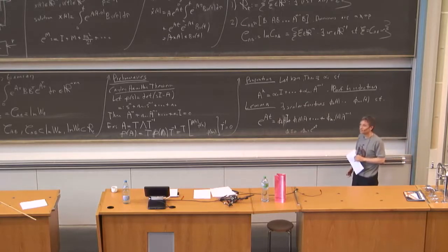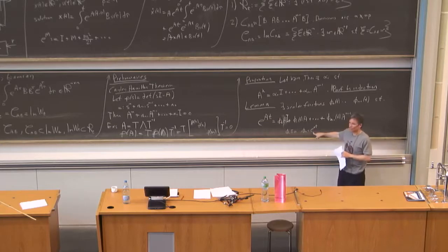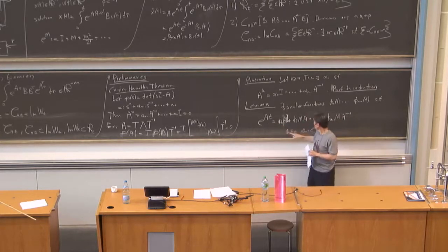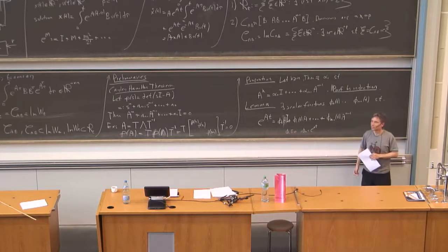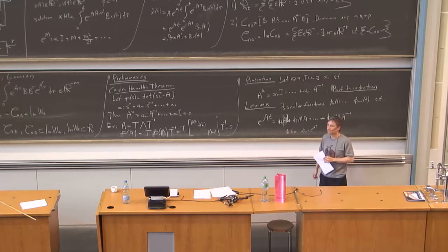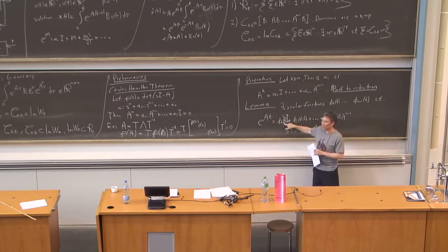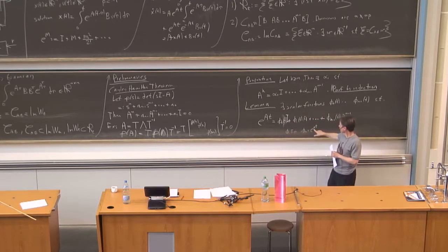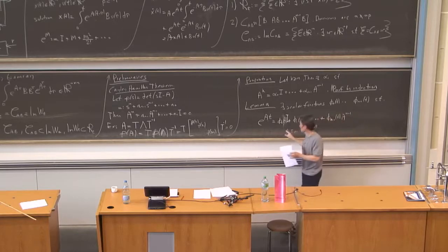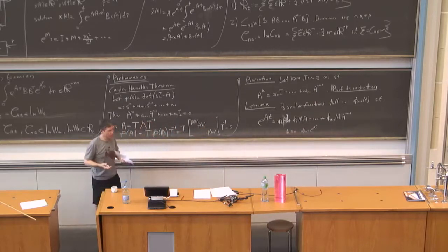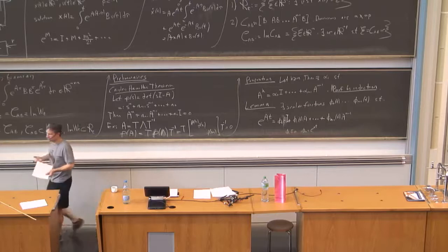I've just given you the answer right here. If A is a scalar, why not just pick all of these equal to 0? E to the at is just equal to e to the at. Exactly, if n is equal to 1, you just get this term here, and therefore pick phi 0 equal to e to the at. I know it's a trivial observation, but when you see a matrix equation that may look daunting, put in the scalar and it should make sense.